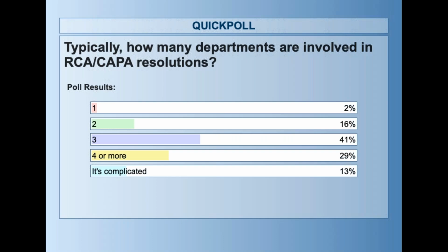For example, some of us who are old enough remember the space shuttle disaster during the 80s. When they went through their investigation, a 5 Why wasn't the appropriate method to get to the root cause of that failure. So they used a fault tree analysis, where I look at the rocket and drill my way all the way down by looking at what the probabilities of this failure occurring at this level are. If we look at it as an inverted bill of material, I'm just going back through the fault tree method to find out why this machine failed. Even though it's a rocket, it's a device, it's a machine.